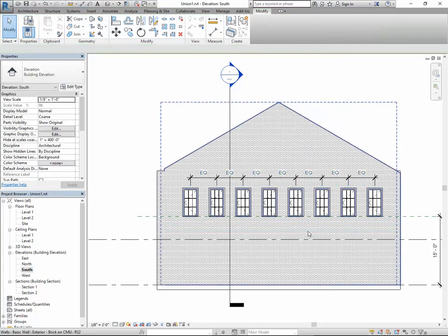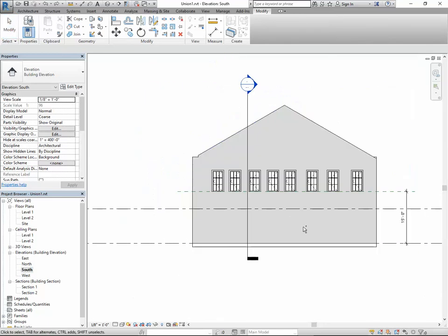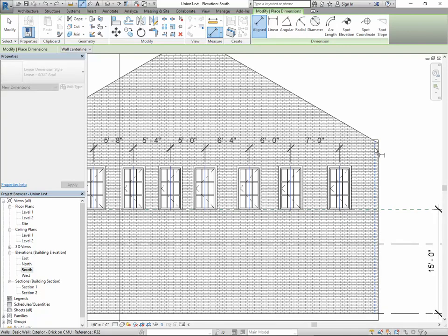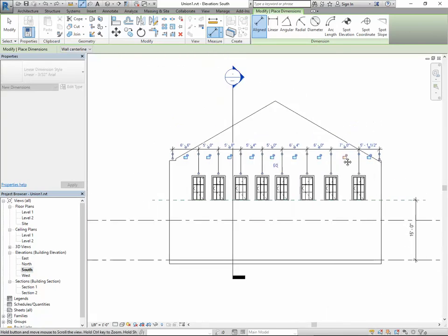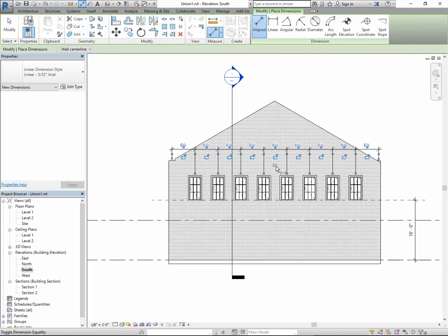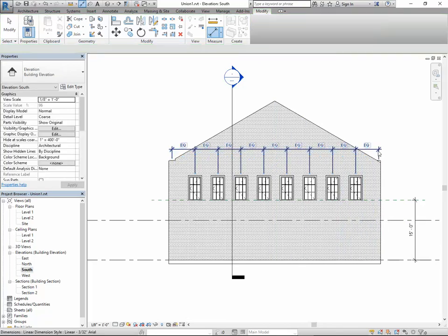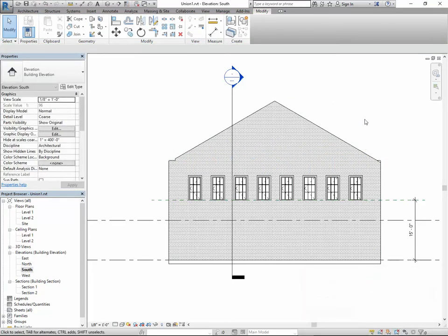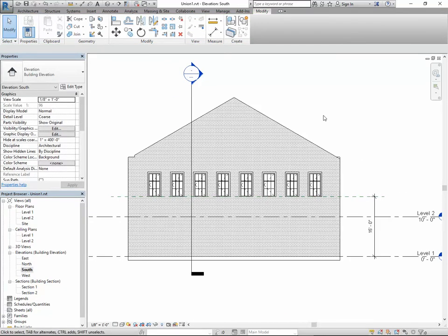So what we could do is Control C that, and DI again from the center of the wall to the window, to the window, to the window center axis, and again to the center of the wall. I don't know if you can see that snapping there. You bring it out, and now we can click on equal, and now all of them have the equal distance, so that they're also centered. We can delete that one. It's going to tell us, are you sure you want to? Because it's actually a constraint that could be interesting to maintain. Well, we're just going to say no.